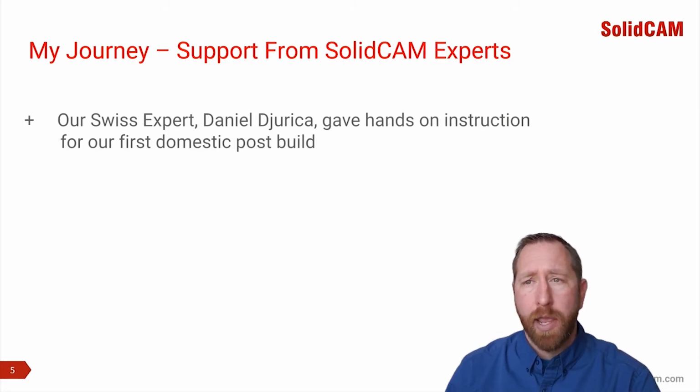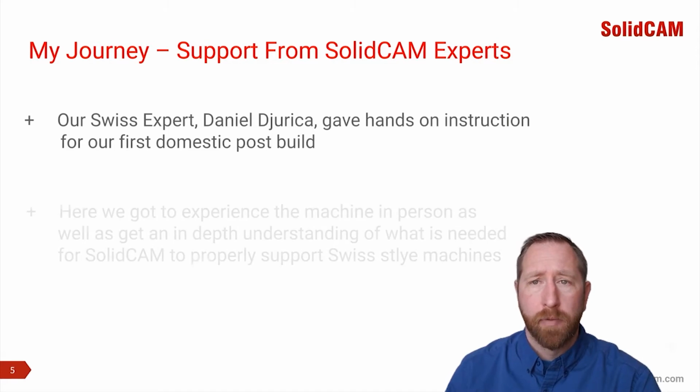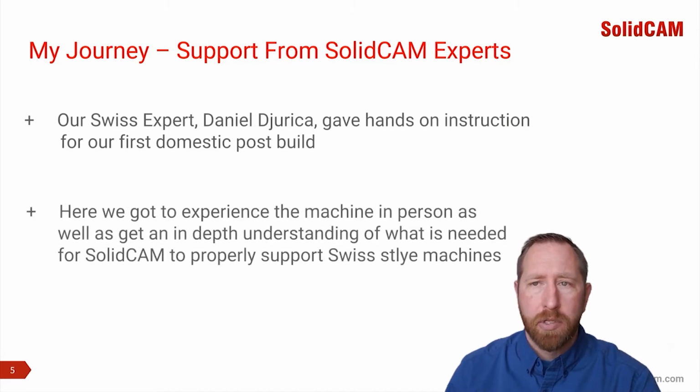Not only was Daniel able to explain what we should be looking for and doing when it came to the post, he also provided instruction for how to properly utilize the machine control operations that SolidCAM uses to program for these Swiss type machines. Here I learned that programming for a Swiss machine can be quite a bit different than programming for a traditional lathe. Care must be taken when structuring the order of operations on a Swiss machine, where ID processes are typically defined first so as to keep the material supported in the guide bushing.